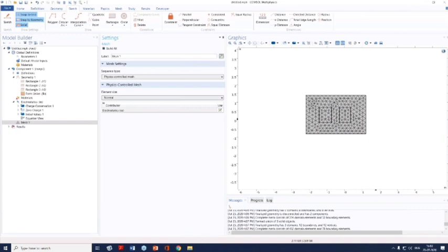However, based upon the physics itself, you can see whether you need to draw all those things in your geometry or not. We do have a Composite Materials module also, which offers various types of theories, and in that case you will not need to draw those layers explicitly. Instead, you can directly provide the composite layer information in the COMSOL physics interface itself, and accordingly the composite will be considered. If you are interested, I will ask my colleague Nitish to send you some example models on composite modeling.